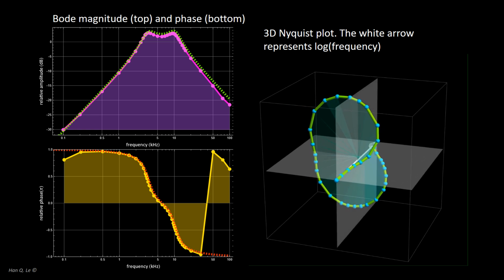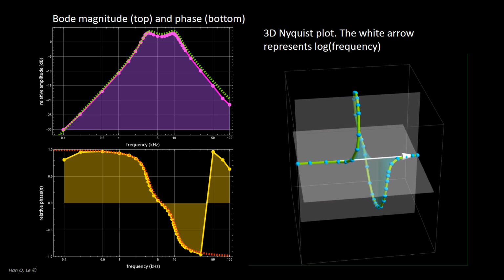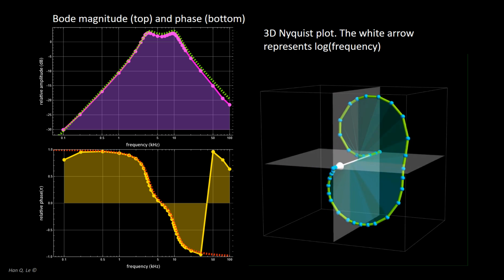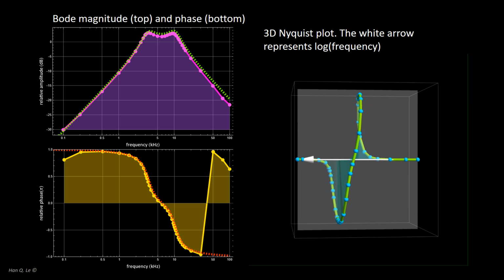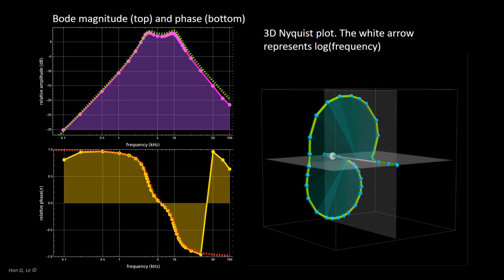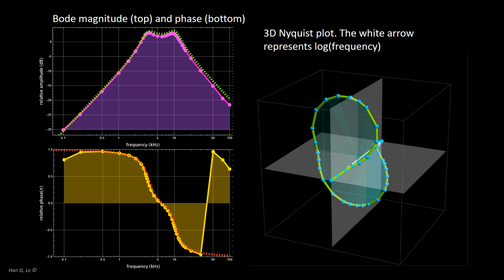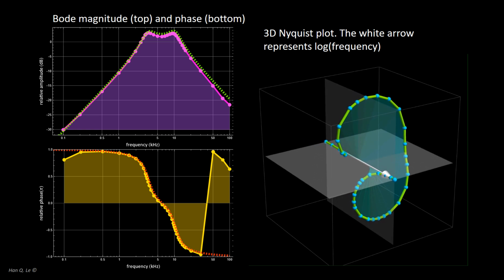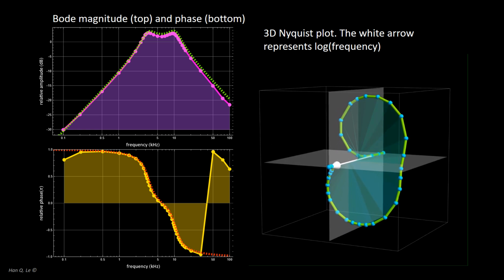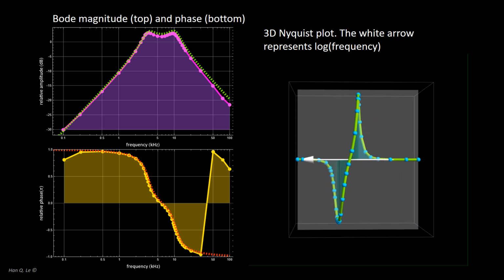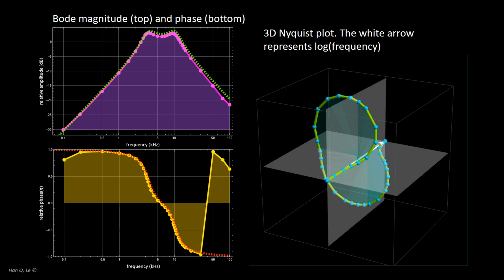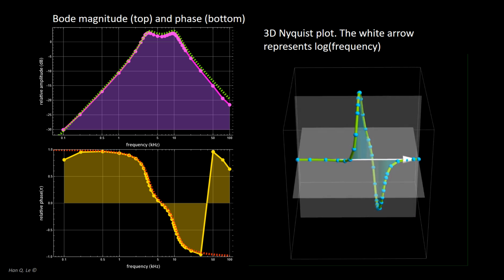For the Bode magnitude and phase plots, the dots and the solid connecting lines are experimental data, the dashed curves are the model calculations. The model does not include the realistic gain bandwidth of the LM741 op-amp, hence there is some discrepancy at the high frequency end. Also, the calculation uses nominal values of the resistors and capacitors, no adjustment was made to fit the resonance frequency.